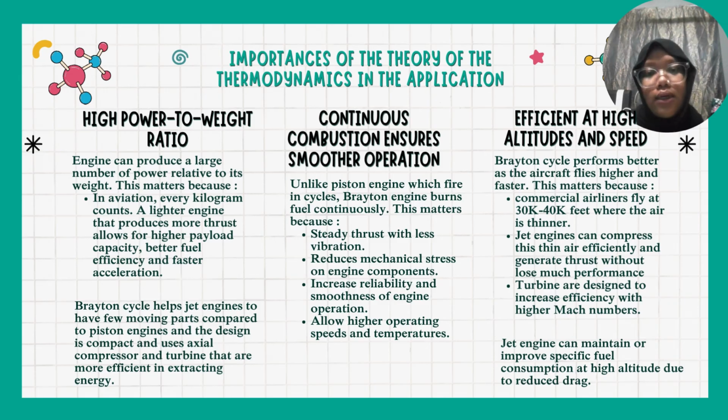The second one is continuous combustion ensures smoother operation. Unlike a piston engine which fires in cycles, a Brayton engine burns fuel continuously. This matters because, first, steady thrust with less vibration. Second, reduced mechanical stress on engine components. Third, increased reliability and smoothness of engine operations. And the fourth one is it allows higher operating speeds and temperature.